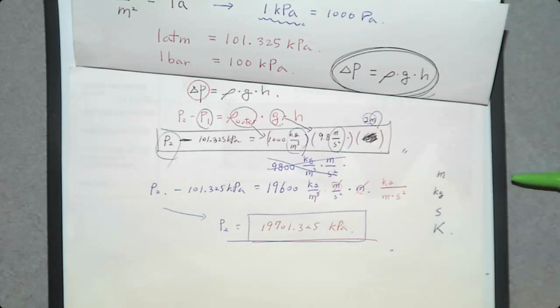So the right-hand side of this equation only has primary dimensions. No problem. What about the left-hand side? We have a Pascal. Pascal is none of these, so it is a secondary dimension. So let's convert this secondary dimension into a combination of primary dimensions.